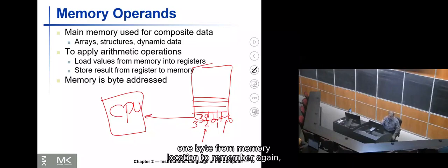But remember again, the memory would be designed in 32 bits because MIPS is 32 bits. It can read 32 bits from the memory. The data bus of the memory and the MIPS would be 32 bits. But at the same time, they need to maintain byte addressability, and it gives the designers a burden to keep it byte addressable.